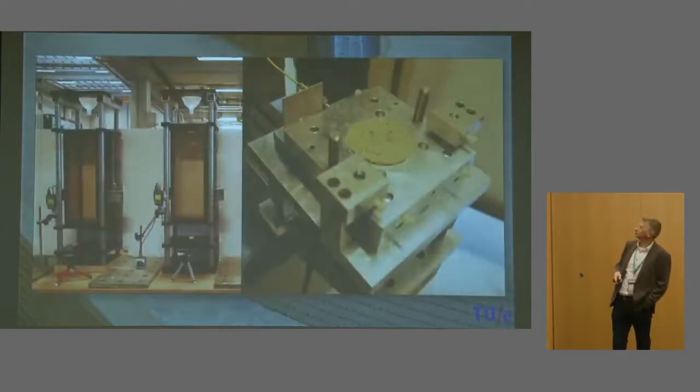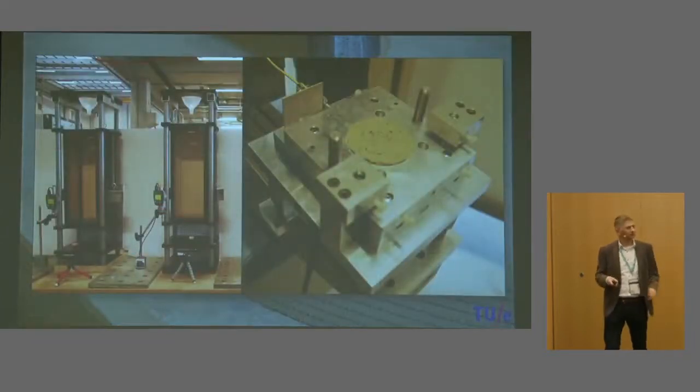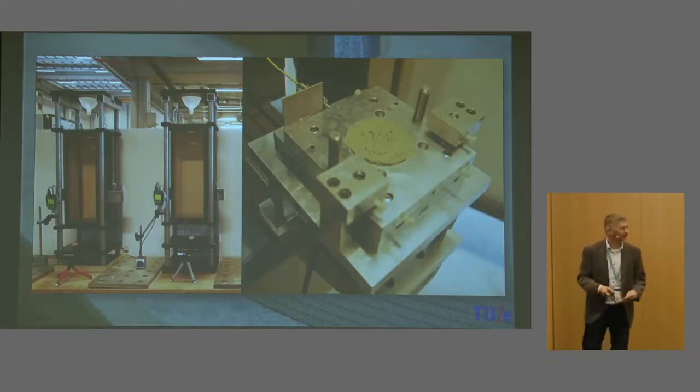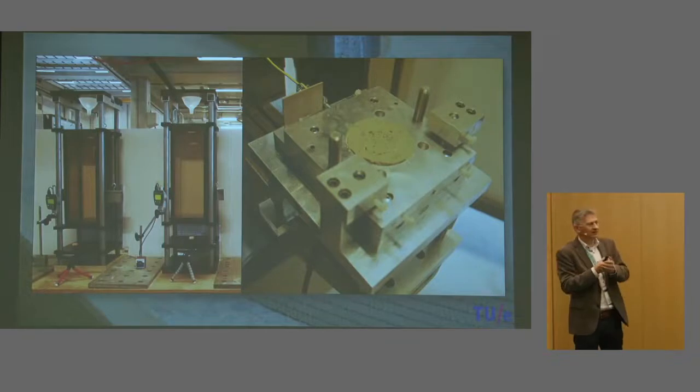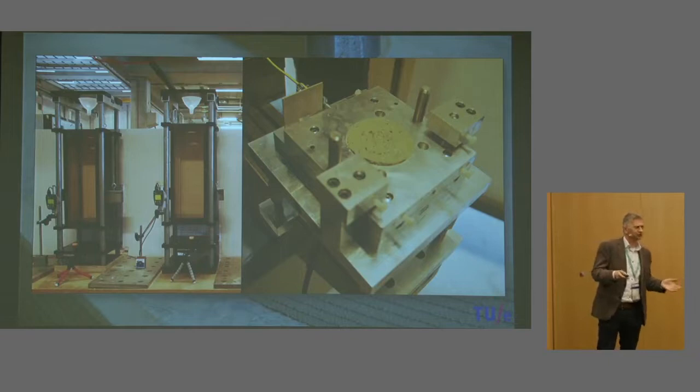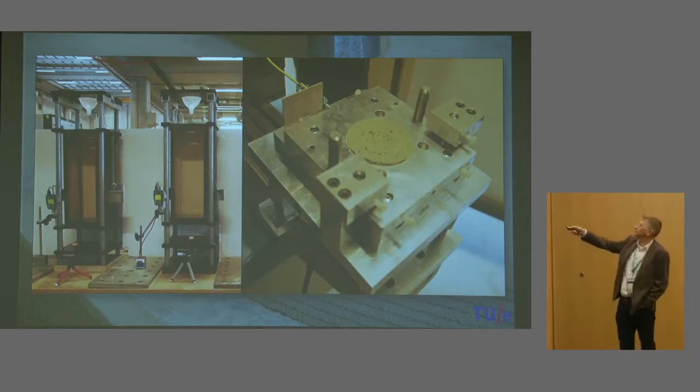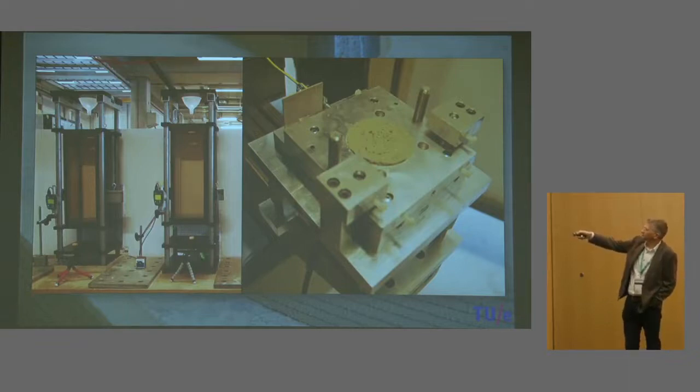So now the research part came in. We need to study not only the properties of hardened concrete, as we do on cubes and cylinders with compression tests, but we also had to figure out the properties of our fresh concrete. How to do that? We just considered it being mud, soil. So we did compression tests on the soil, sand in here, a sample underneath, a kind of a measuring device here, a load cell to measure the force coming from the sand, and a displacement. This is in compression, this is in shear.